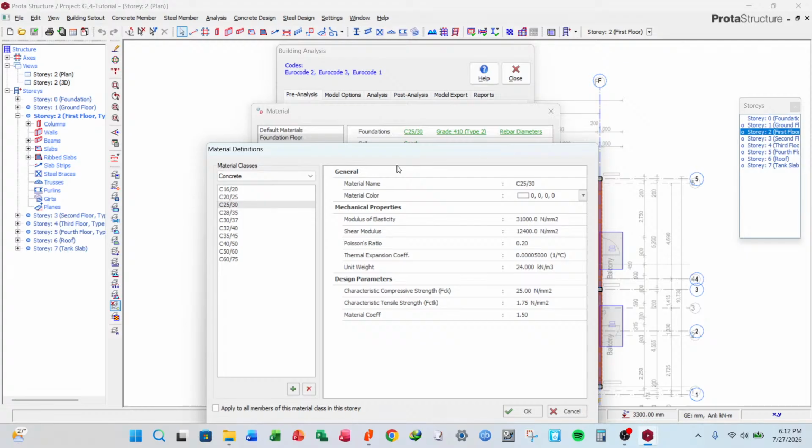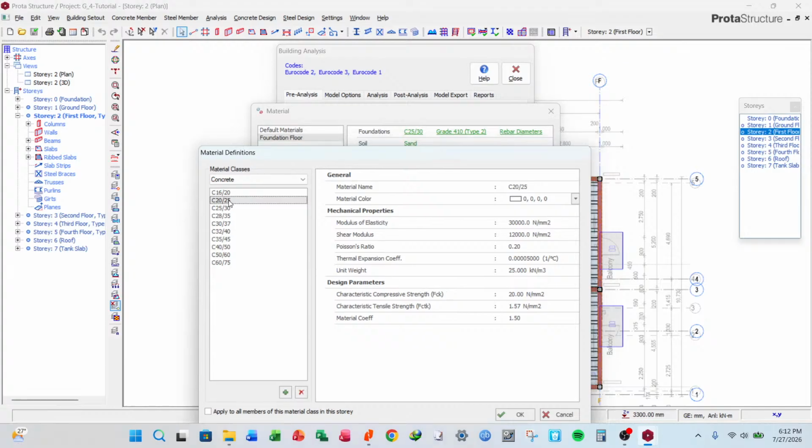So here, based on your exposure, if your project has a geotechnical investigation report, you have to calculate for the grade of concrete. There's a minimum grade of concrete based on the soil conditions.